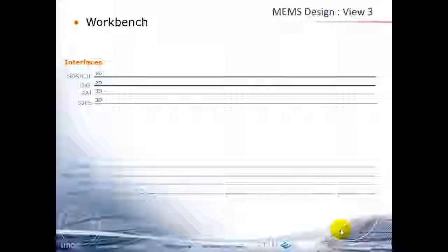It was a trial to define a standard, but it's not a successful one because everybody had to implement their own standard. If you have a 3D model, you export it to IGES with one package and you import it into another package, I'm not sure you will get the same shape again. So you have to rely on the code from the 3D models themselves, but that costs you some money extra.